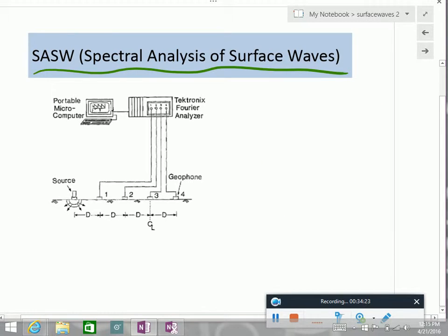It's clear that the way an earthquake amplifies and comes to the surface has a lot to do with the shear wave profile near the surface. So civil engineers are very interested in the shear wave profile near the surface to be able to see how the shaking from the bedrock is amplified when it gets to the surface. It kind of works as a transfer function going from bedrock all the way up. And that's why you need this kind of shear wave profile.